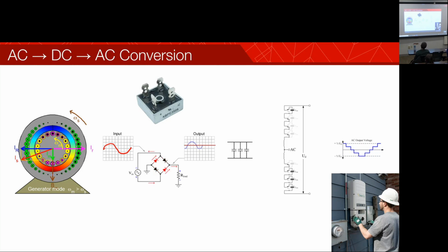And so if you are buying an inverter for your car so that you can go camping and power your whatever, especially if you're powering an audio system in your car, you probably want a pure sine wave inverter. Otherwise what might happen? Essentially you'll end up with noise. Not just white noise, but noise probably around a 60 hertz hum. You ever notice in an audio system, especially an analog audio system, you'll hear a hum.